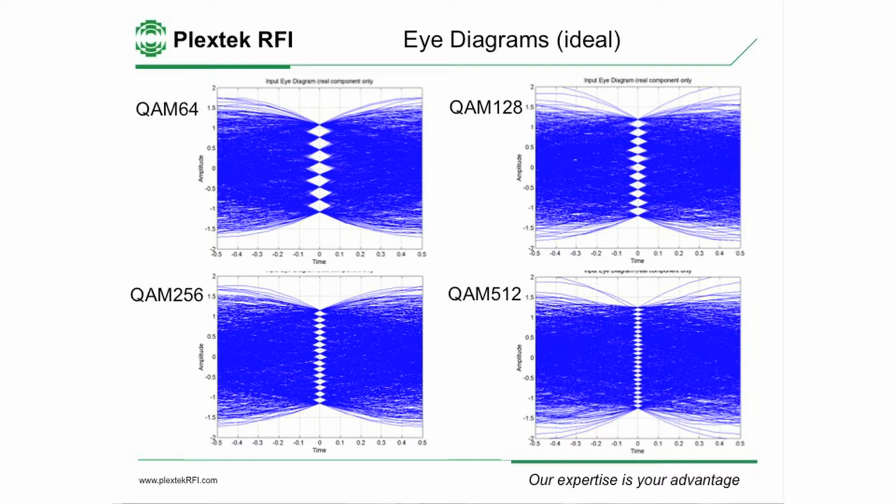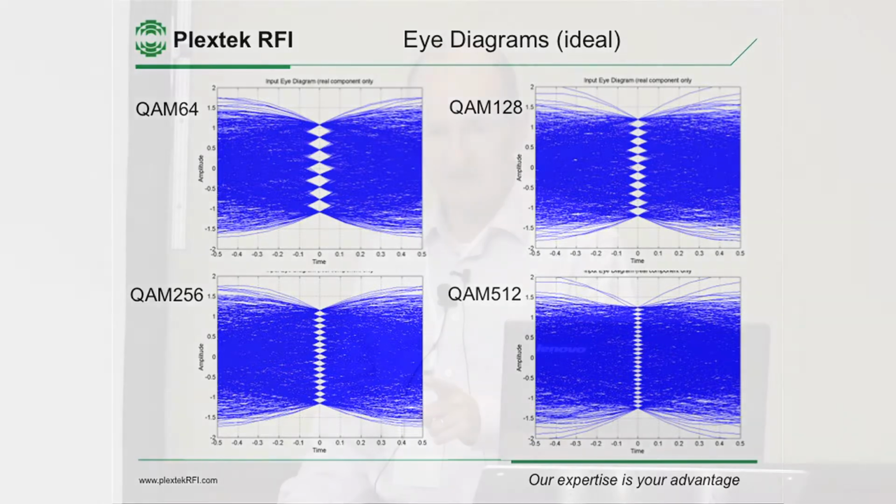We transmit it, it comes in the receiver. We have another root-raised cosine filter in the receiver. So overall, we have a raised cosine filter. And what that ensures is, at the sampling instance here, and only at the sampling instance, we have no ISI, intersymbol interference. Everywhere else, these root-raised cosine filters actually cause intersymbol interference.